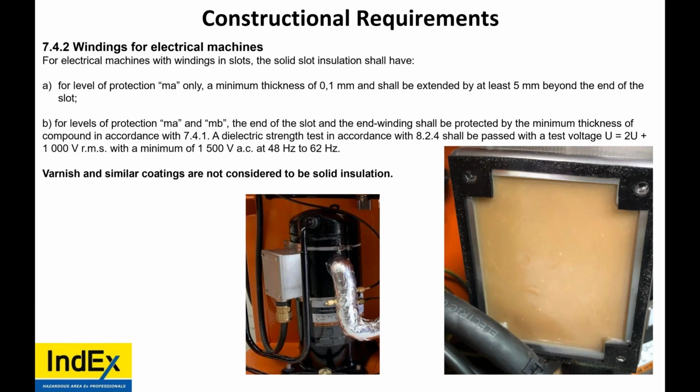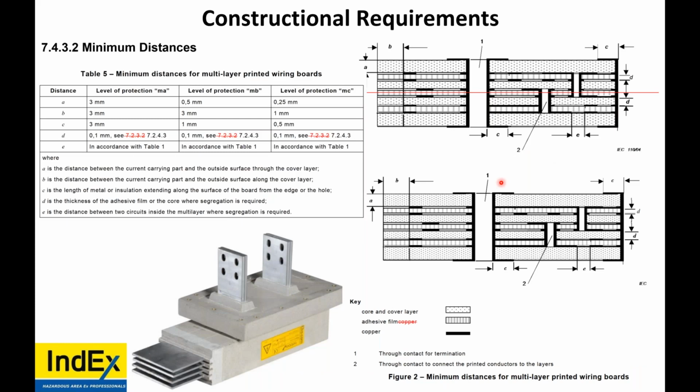Now, what did they do with this compressor? To make it EX, they poured encapsulant into the enclosure. This one is IECEx rated. They took a standard compressor and plugged the hole between the body of the compressor and the enclosure by using encapsulant. Ingenious idea. Now, when we're talking about the slots, look at all these plates here. Just to give you an idea.